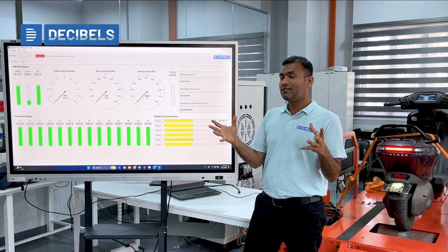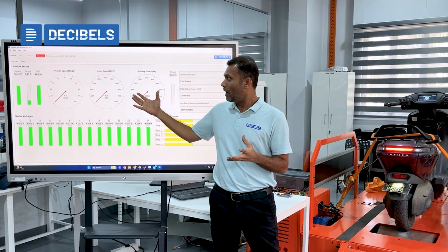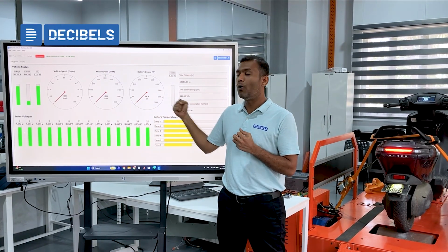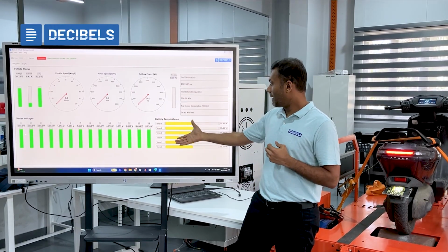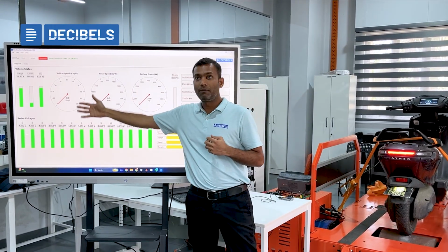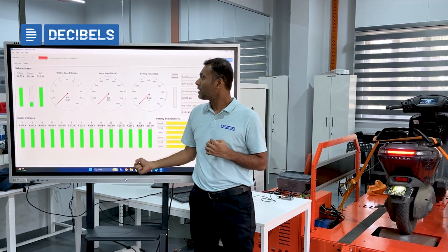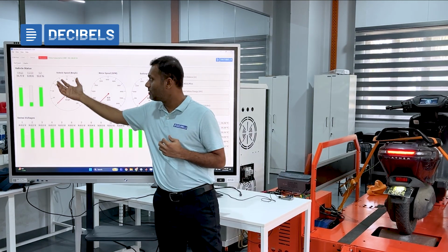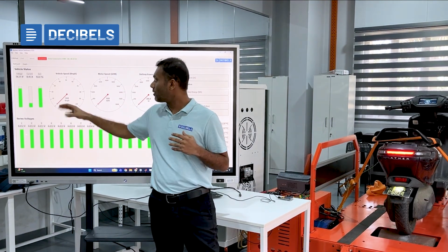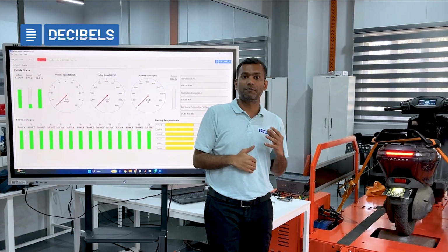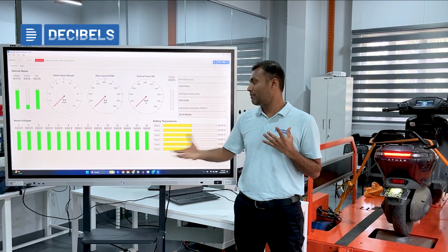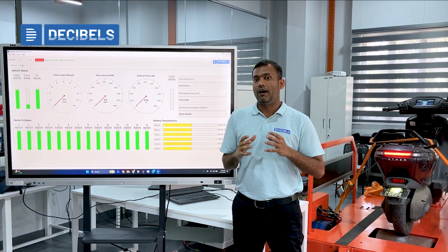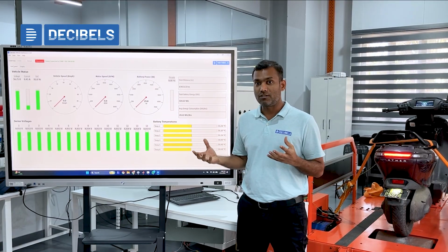And apart from these things, there is also an opportunity to learn about how OEMs have developed certain de-rating compartments. Let's say the battery temperature goes up, how does your vehicle performance reduce, right? And in the different modes, the more the temperature rises, how does your vehicle limit its performance so that it doesn't overshoot any of the battery temperatures or make the vehicle go into unsafe conditions?